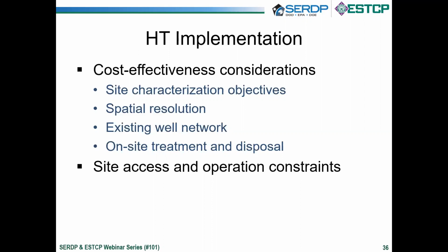If you already have a treatment facility on site, the extracted water can be treated without much additional cost. But if you don't have treatment facility available, you might have to put in some cost to account for cleaning or treating the extracted water. Or alternatively, you might be considering injection of clean water to generate the hydraulic signal.